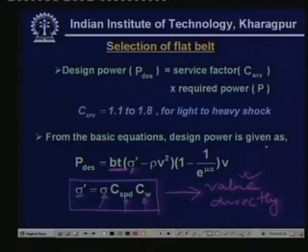So, what do you get from this design equation? You know this value from the design data book, you know this value from the design data book. This is your choice of the speed. What should be the choice of your speed? Say roughly 20 meters per second. And this thing you get from the material property, and this alpha from the geometrical property.